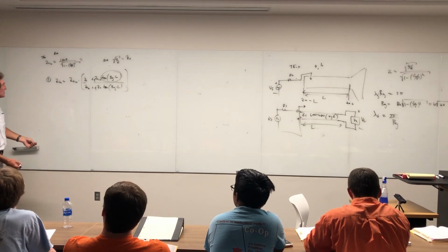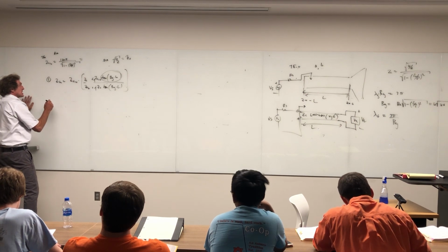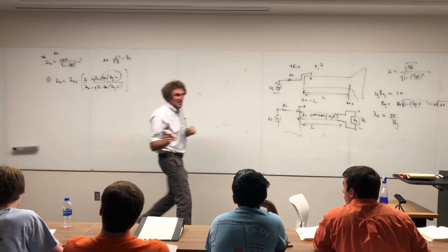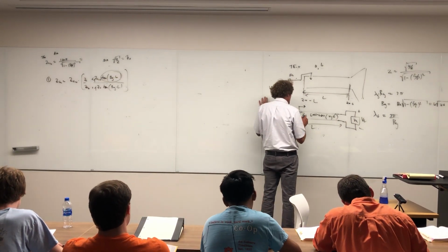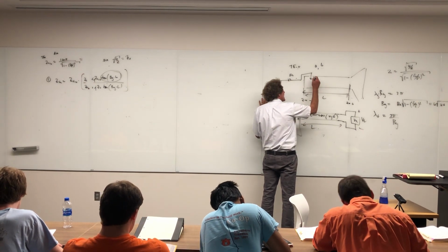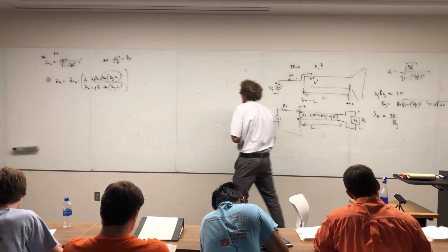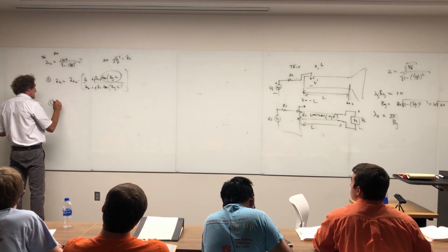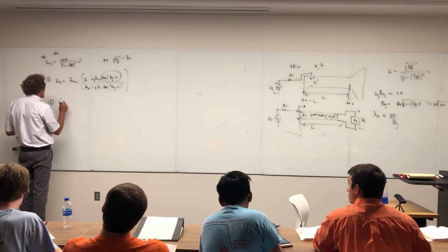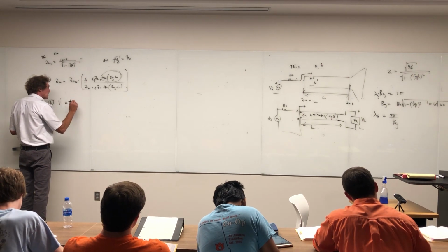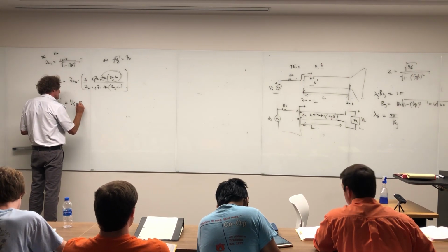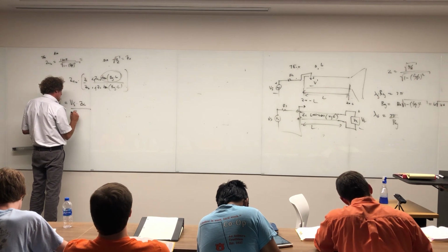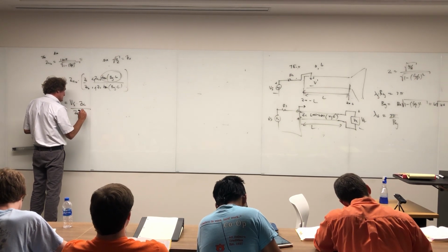At this point, we say that the voltage, I know it's really an E field, but it's a measurable voltage too. The voltage just inside here, I'll call it V prime. Now we say V prime will be equal to the source voltage times Zin over Zin plus Rs.